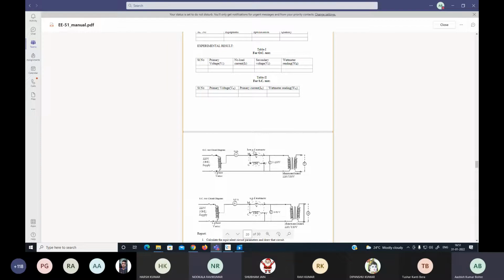Okay. Now whatever is in series, after this M point towards the load, you see this is ML. So ML is basically the current coil. And parallel to the voltmeter, you can see this is MCV. CV is the potential coil, or voltage coil. It is a very easy concept to remember. Here one voltmeter is connected in parallel on the input side, and you see one V terminal is also there. It means CV is the potential coil. Yes, thank you.